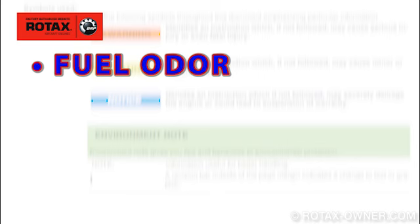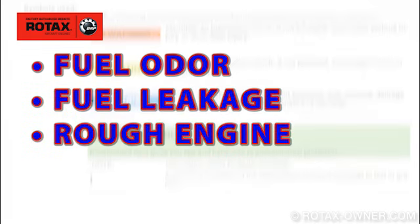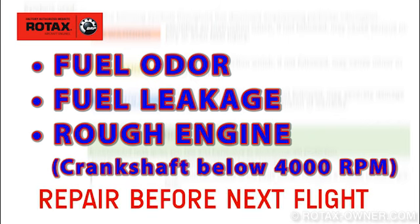In the event of fuel odor, fuel leakage, or rough engine running, especially at low engine speeds, crankshaft speed below 4,000 RPM, you must carry out this inspection before the next flight. The cause, which may be independent of the floats, has to be fixed before the next flight.